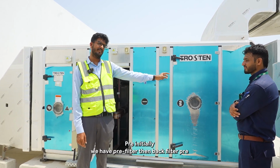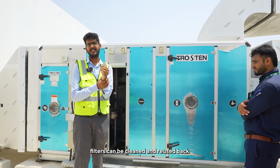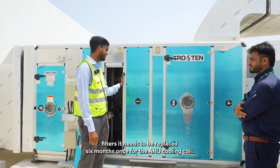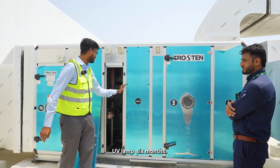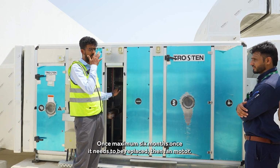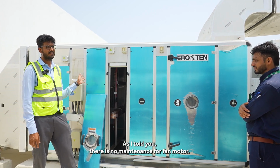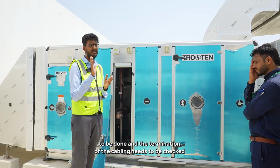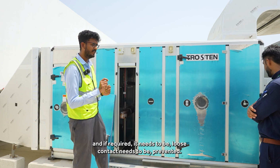Initially we have the pre-filter, then the back filter. Pre-filters can be cleaned and reused. Back filters need to be replaced once every 6 months for the AHU. For the cooling coil, if the filters were regularly maintained, it can be cleaned once a year. The UV lamp needs to be replaced once every 6 months, maximum. Then the fan motor, as I told you, has no maintenance. Only the cleaning of the housing needs to be done and the termination of the cabling needs to be checked, and if required, loose contact needs to be prevented.